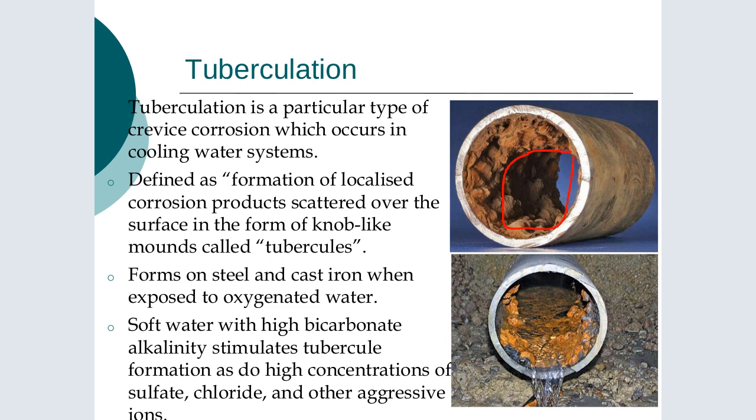So it's at an angle there, skewed. So you've got a 50% reduction in the diameter. Now you might think, well, so what? But you can see when we're designing piping systems that you'll design this diameter to be optimum, and it will be tied to your selection of your pump. So your pump behavior and your pump efficiency will be linked to the size of your pipe diameter and the flow resistance going through it.